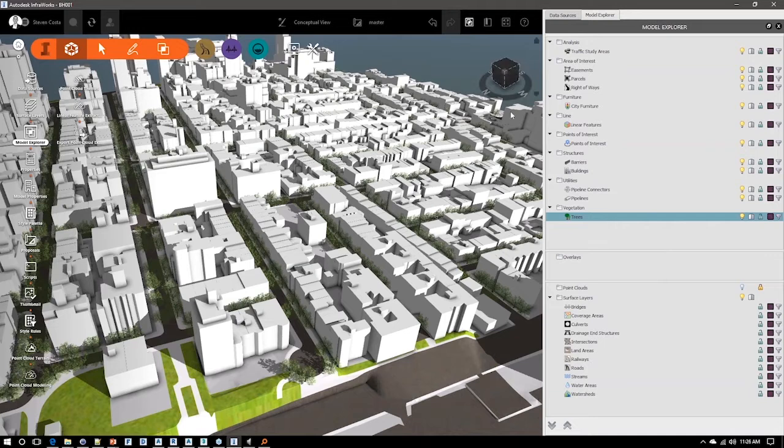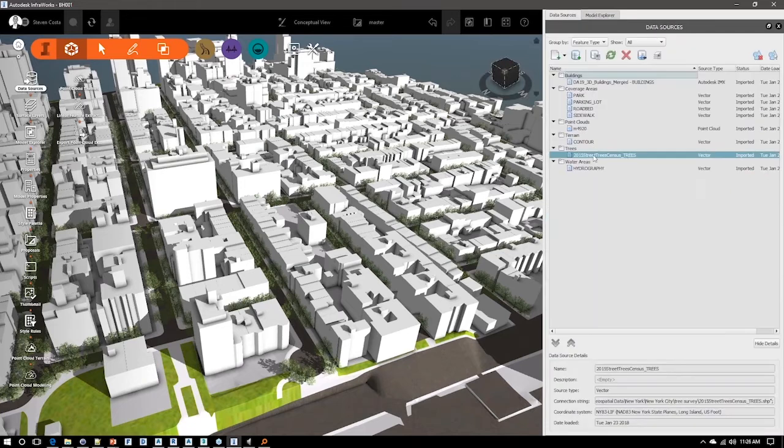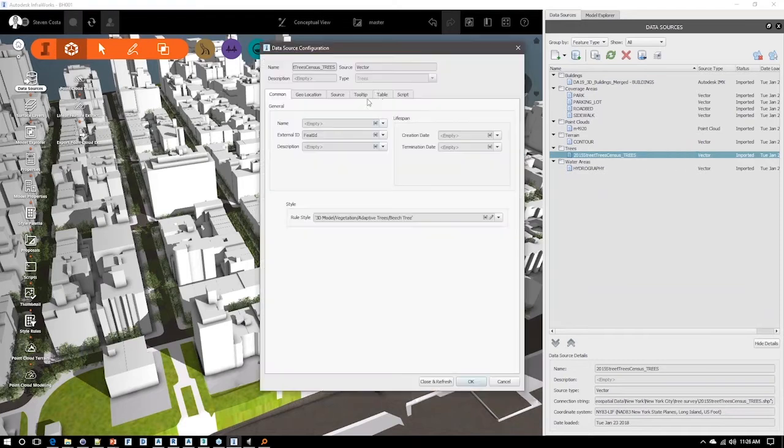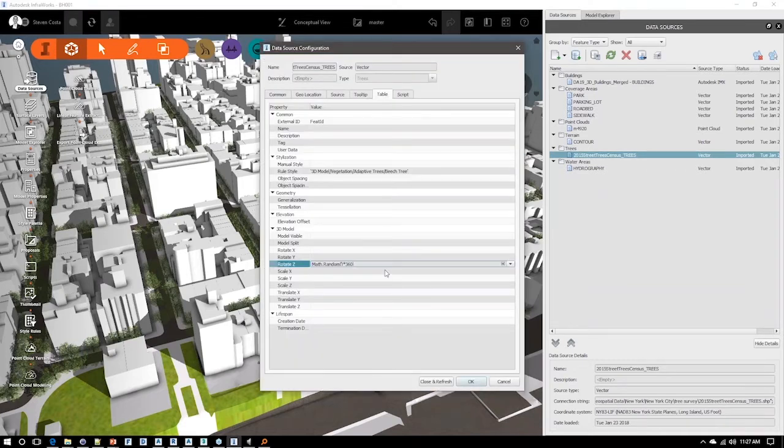One quick little note that's useful for randomization of elements like this within an Infraworks model, to add that little depth of realism, is to add a little JavaScript to the rotation axis. So along the Z-axis, I can rotate, and I can specify a random number between 0 and 1 and have that multiply against 360 degrees.